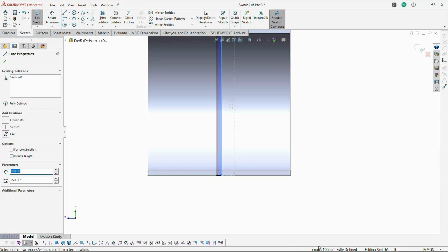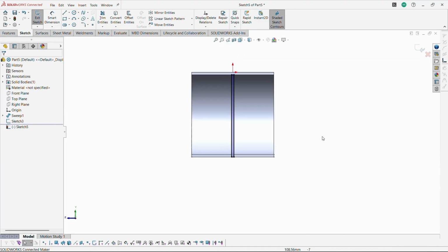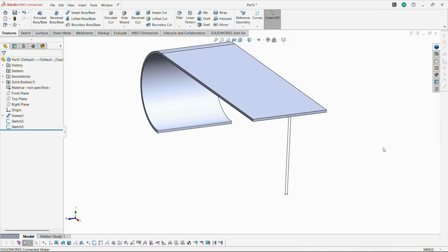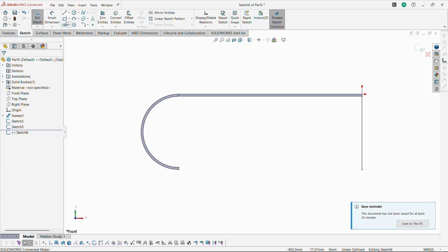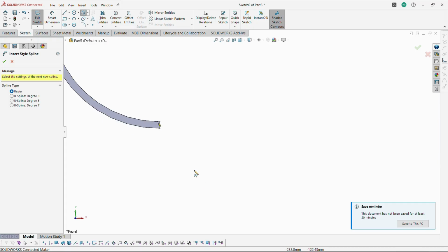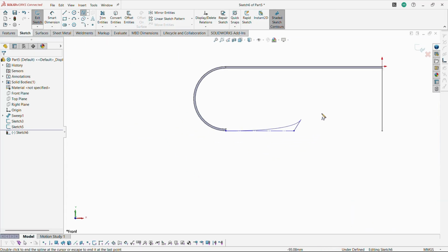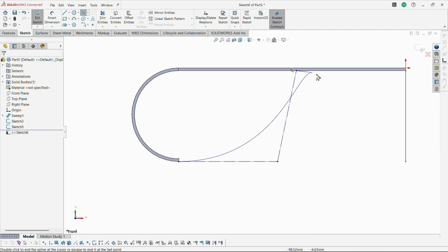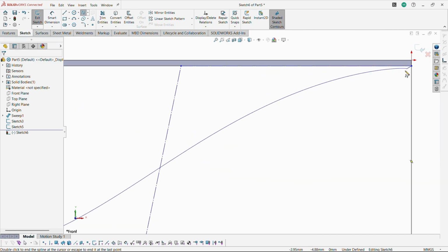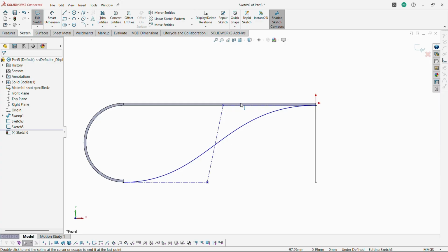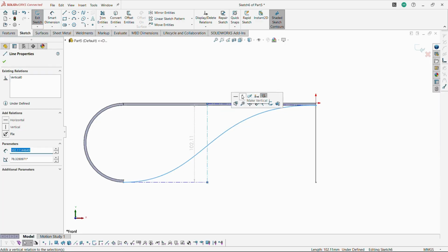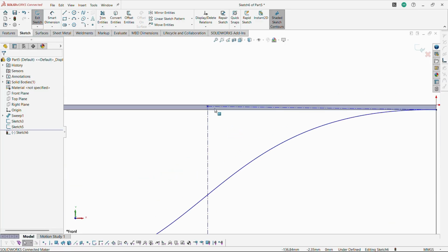Afterwards, I just switch this point to its end point. The vertical dimension is nothing but 100 mm. That's why we just get it from this dimension area also. Once it is created, use a front plane to create a new sketch called a style spline profile. Here we have 3 different points: first point, second point and third point. The 2 end points are fixed with the 2 different end sketches.